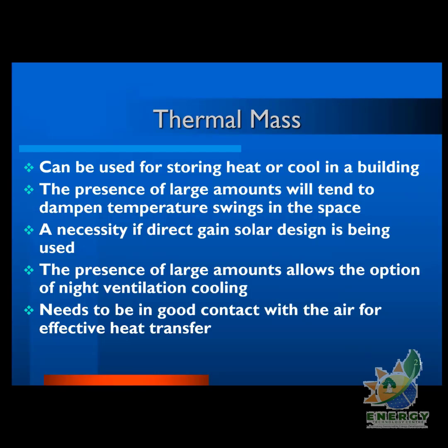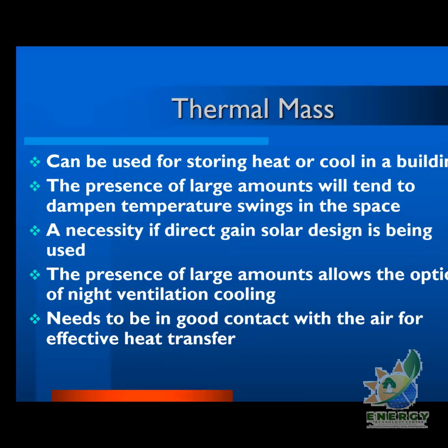You can also absorb a lot of the heat during the daytime when it's very hot, and during the nighttime when it's cold outside, it's possible to have ventilation so that the heat would be emitted outside. Now, thermal mass is also another important factor that has to be considered in the design and construction of building, and it can be used for both cooling and heating purposes.